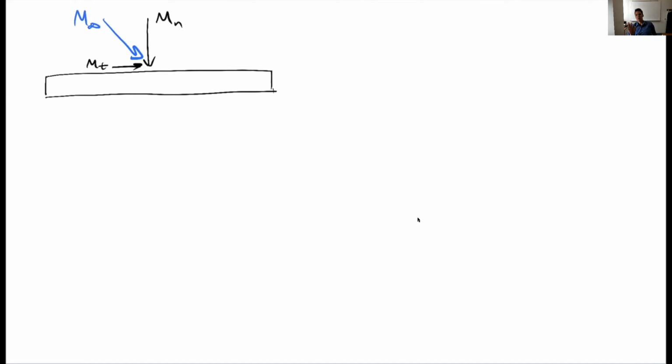Or another way to think about it, if you don't like the moving wing thing, let's say instead of having the air come normal, I put it at this angle. So there's a normal component and a tangential component. Because there's no viscosity and it's an infinite wing, that tangential component contributes nothing. It doesn't change anything about the behavior of each airflow section. There's no way it can because it's infinite, right? And there's no viscosity for, say, a boundary layer developing spanwise.